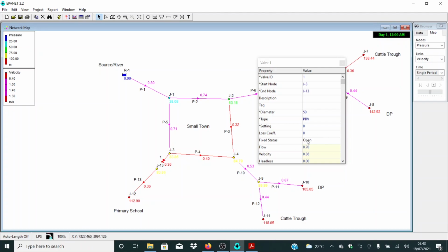Okay, but as soon as I introduce this PRV, or pressure regulating valve, you can see if I set here none. Okay, so as I said, if I set none, I'm going to command my valve to operate under this pressure. So let me select none. Again, this is what we are having. Okay, so you can see now I don't have 112 as a pressure again. So for now I have almost 3 bar, which is 30 meters of water column.